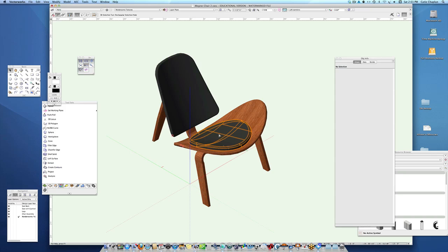We'll extract a curve and then use the shell from the seat to create the cushion. We'll trim it using the project tool. We'll use shell solid again to give it a thickness, fillet edge tool to round over the edge, and then we'll have a nice cushion that matches the contour of the seat.